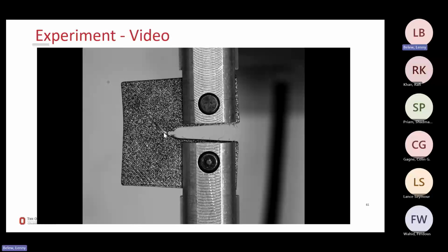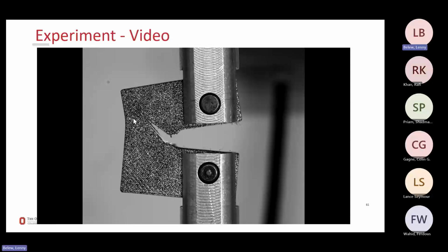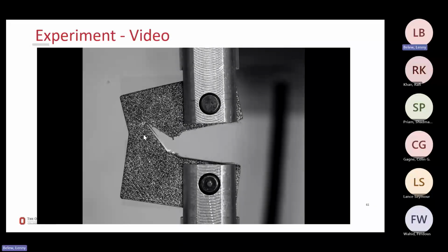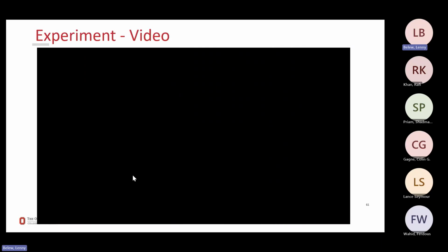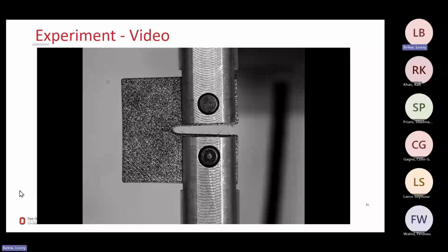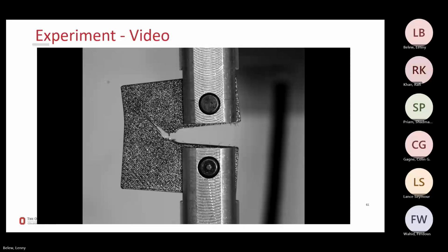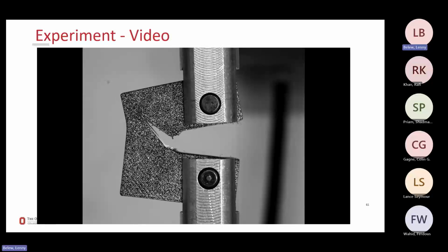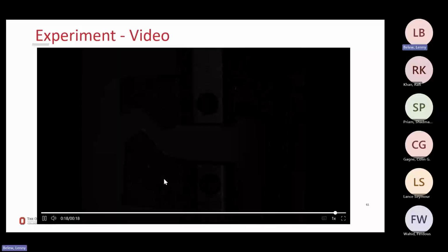So you can see here the crack starts to grow, and then it'll kind of stall out right here. And when you see the large amount of bending here, this will actually snap in a different direction, and then it snaps apart. We'll dive into that a little bit more later. But again, just with my mouse out of the way, there's the same video again. Fairly constant rate for the first crack propagation, pretty smooth, and then it gets kind of messy towards the end. Messy and quick.